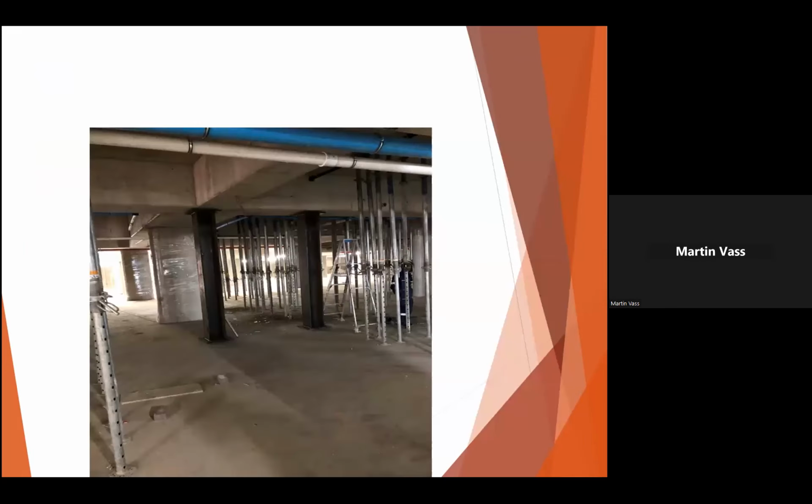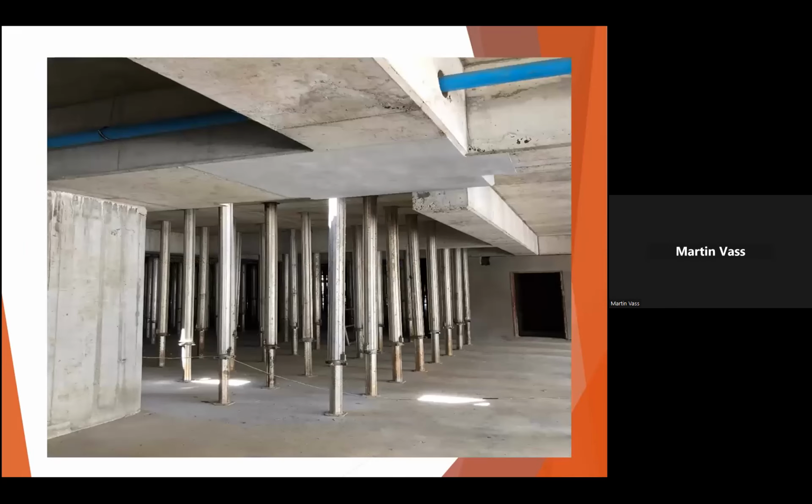I'm going back now. What you see there are the beams above, and in some cases, those are what you call transfer beams. When they had constructed 4 levels of the 7 levels, some of these transfer beams started to crack. They started to fail. And if you don't have the full load of the building on, and beams are already cracking, then you know you have a problem.